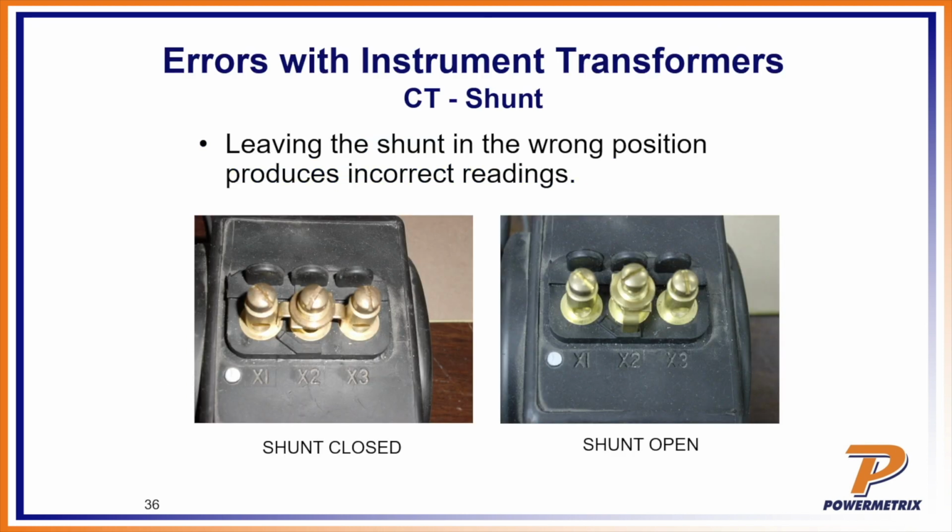Errors with instrument transformers. One of them can be a shunt problem. If you leave the shunt in the wrong position, it produces incorrect readings. Now, it doesn't produce a 0 reading, but it produces a low reading. And I won't name any names, but I do know of a situation that happened in a state near Tennessee. And what happened is some work had to be done at a particular site, and one of the CTs was not completely opened when they left the site.